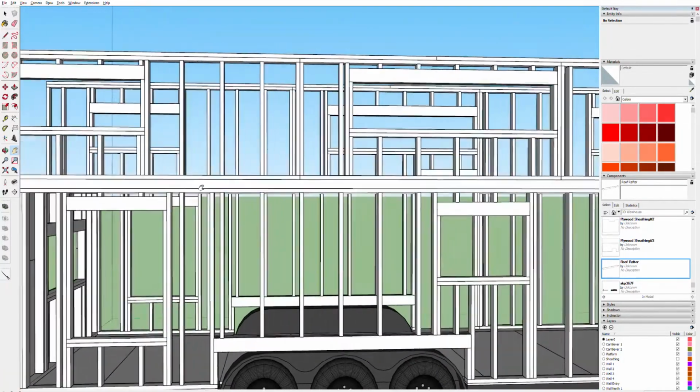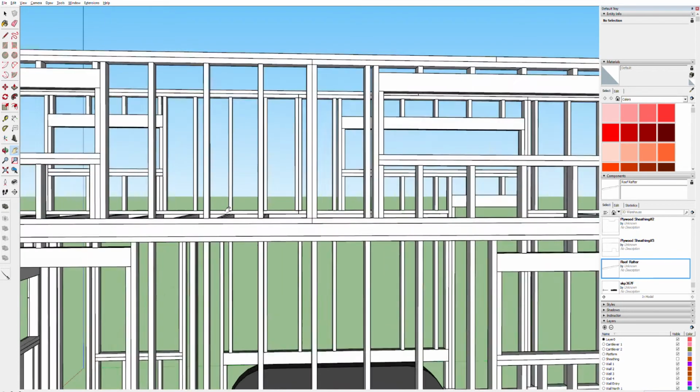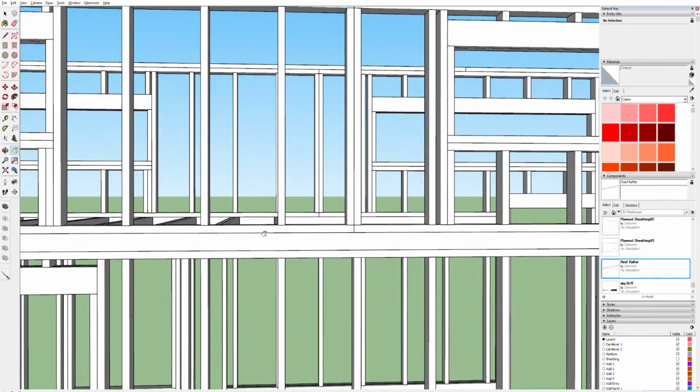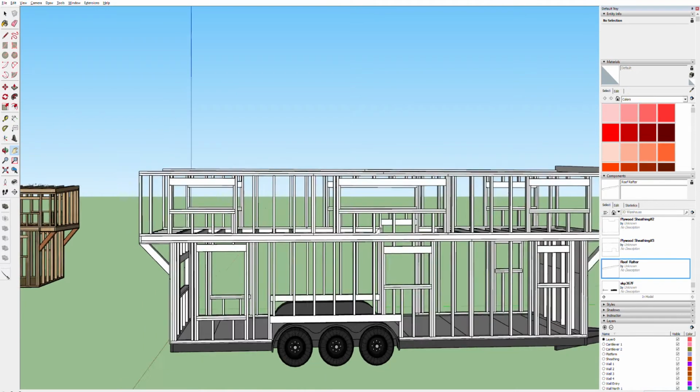What I didn't want, when I was framing these walls, even though I have a platform here to spread out the load of each of these load-bearing 2x4s from the roof, was to land one in the center of two framing members down below, two studs. Even though maybe that's okay, because that's the purpose of this platform, to spread that load out, it's nonsensical to do something like that.